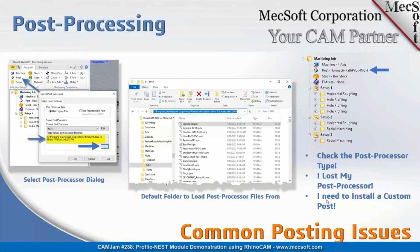So we have three items down here that people run into. The first thing is you want to make sure in this dialog on the left that you have the post type defined. In most cases, you'll be using what's called our legacy post. And this is the list of posts that you see here in this default path. In most cases, you'll be using one of those post processors, or you'll be starting out using one of those post processors. So make sure that you have it set to use legacy post so you can access all of our predefined posts that come with the product.